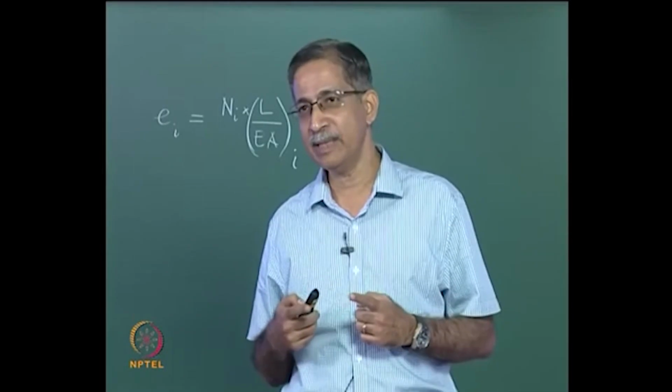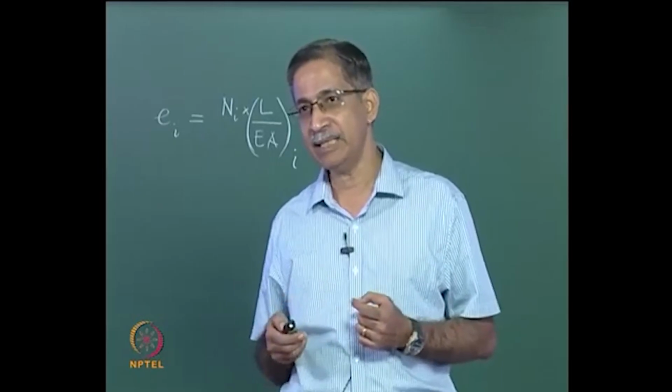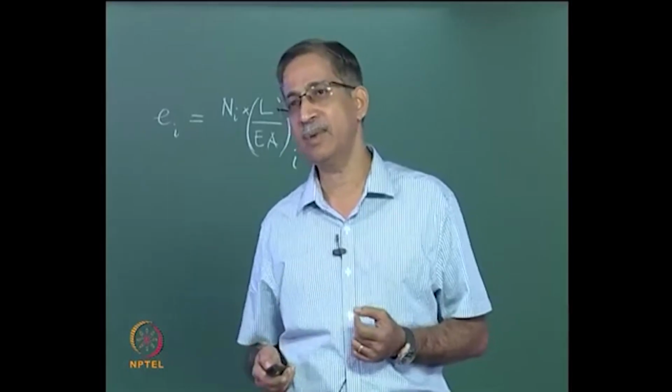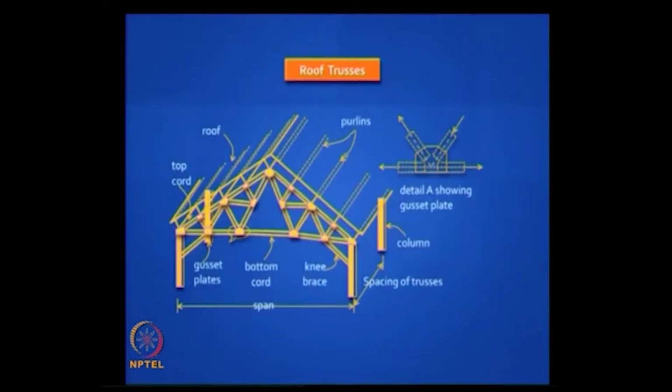So the only way to do that is to rotate AB about A and CB about C till they meet, and you can draw arcs or tangents to do that, and that is how you locate it geometrically, and you can actually get the deflections, but we will find there are better ways of finding deflections.